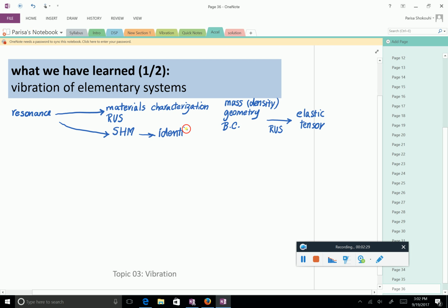We looked at the bridge together, and you also saw that it can be used for looking at a building after an earthquake, like a post-event assessment of structures. You can look at how the resonant frequencies and the mode shapes have changed, and that gives you a global understanding of what's going on in that structure. So these are the motivations of this.